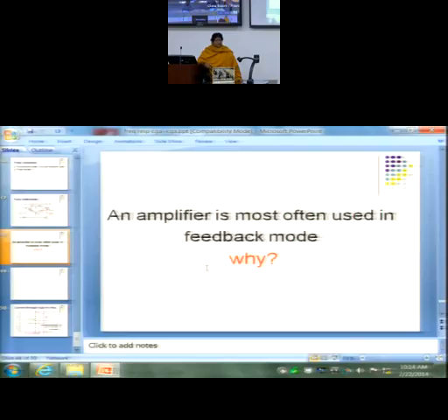I'm saying you will get a gain of 10. This is what we achieve through negative feedback. That is why, mostly because of reliability, process variations reduce to virtually nil. The effect of fluctuations reduces to virtually nil. This is what we obtain through negative feedback.